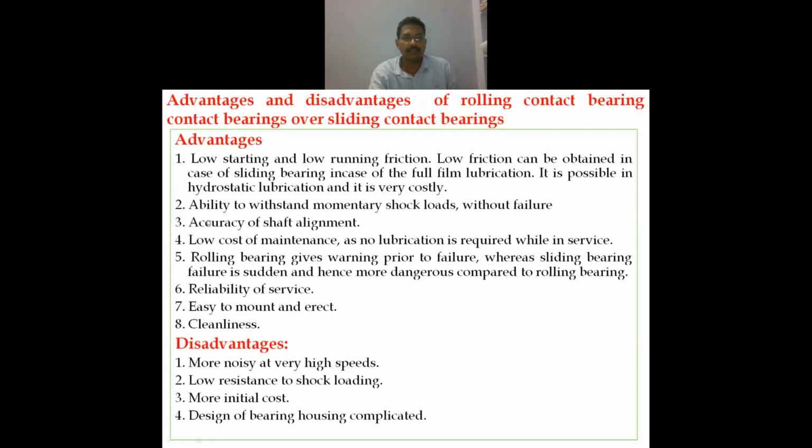Now other advantages of rolling bearing are the ability to withstand momentary shock loads without failure, accuracy of shaft alignment, and low cost of maintenance as no lubrication is required while in service. Rolling bearing gives warning prior to failure, whereas sliding bearing failure is sudden and hence more dangerous compared to roller bearing. Reliability of the service is one of the advantages of rolling contact bearing. Easy to mount and erect, and cleanliness.